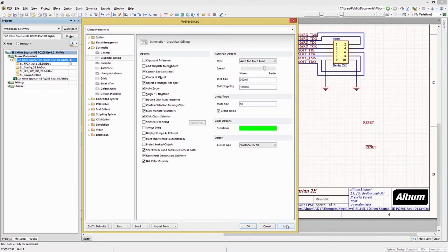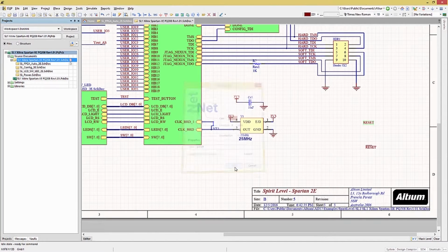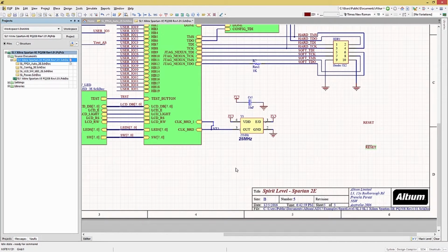Let's open up the net label property for this so that we can see the single backslash that's causing the overbar. Note the other label only has the first three letters with an overbar. Looking at its net label property window by double-clicking on it, we can see why. If instead of a single leading backslash we employ multiple backslashes in line, we get the effect of placing the bar over some of the letters but not all. Please feel free to experiment with this. By the way, this use of multiple backslashes is not affected by the Preferences setting.